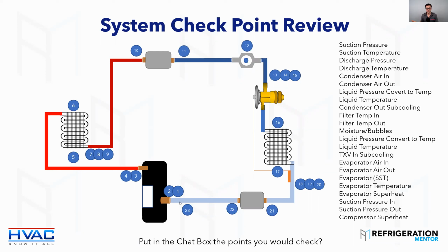Is that suction line insulation bad? Is it running through something hot? Is there a restriction? Trevor, it's the TXV. It's the TXV. Yeah, let's adjust it. Let's open it up. Okay, but you want to understand what's going on, because I've seen it many times.